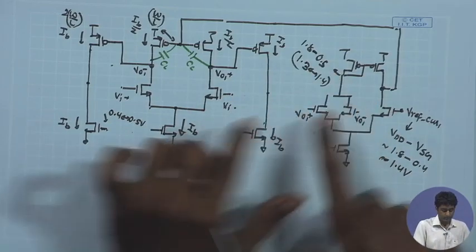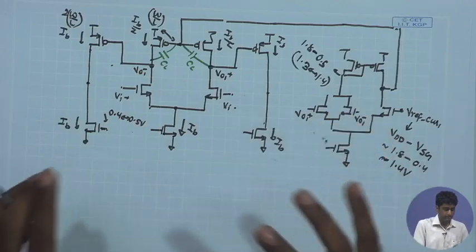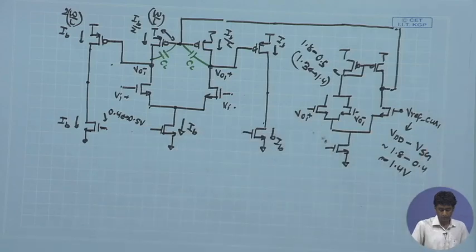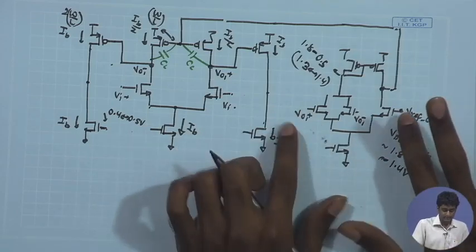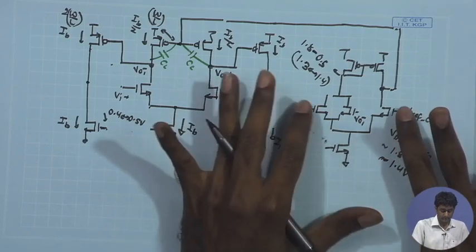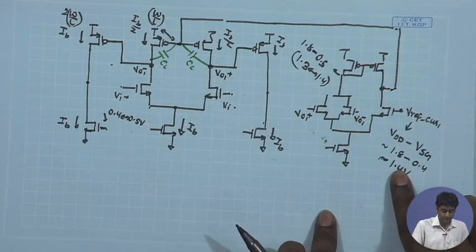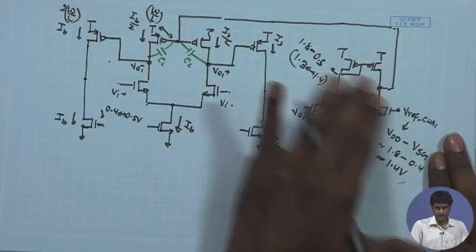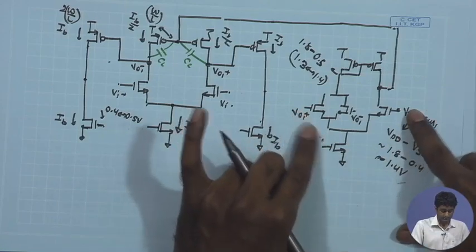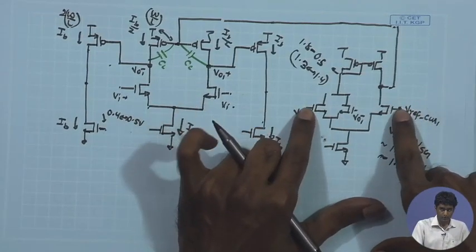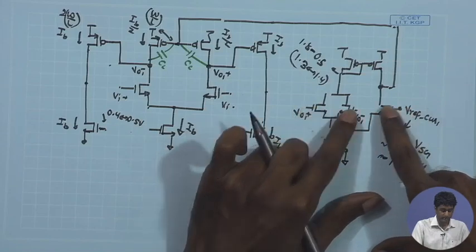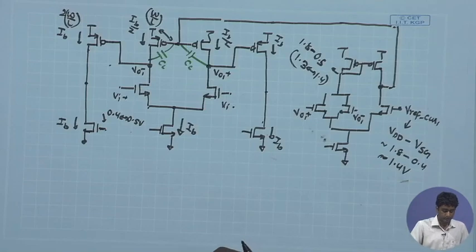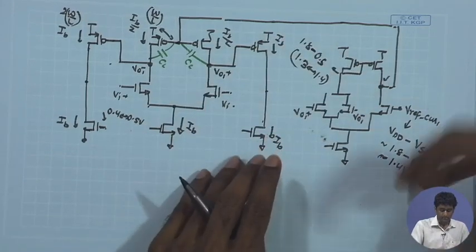and therefore, under steady state when you have a common mode stable, the effective common mode input coming at these two inputs is also going to be around 1.4 volt. Is that safe enough for this device? Whether it is going to operate properly with such a large input common mode value also needs to be verified. So, if I look at this amplifier in isolation, the maximum common mode level that you can have for this amplifier, that is the maximum common DC level that you can have for the input device over here and here, is going to be determined by the Vd plus mod Vt.